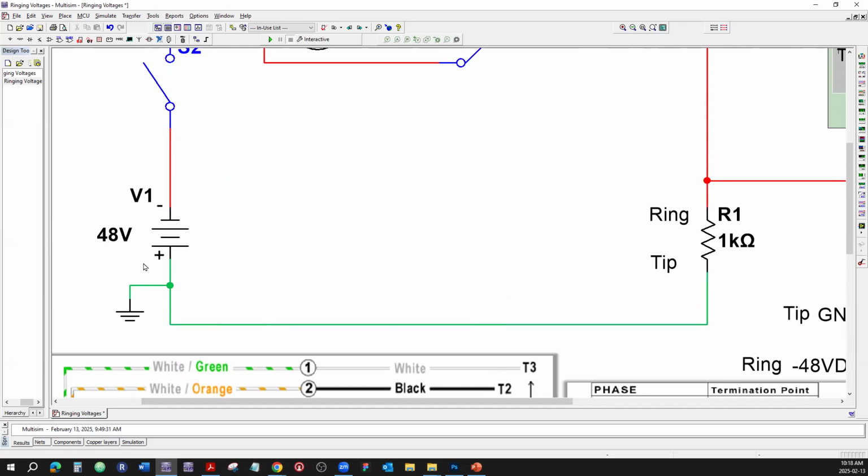that I'm introducing you to, is that when you are troubleshooting a telephone line, you're looking for two things. You're looking for dial tone, and you're looking for the battery. The battery means that there's 48 volts between those two lines, between tip and ring. And a dial tone is like, listen to it.